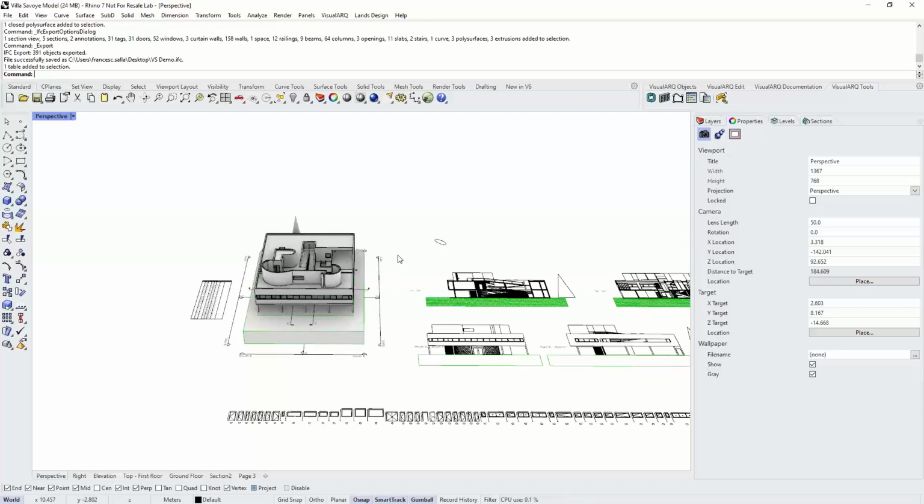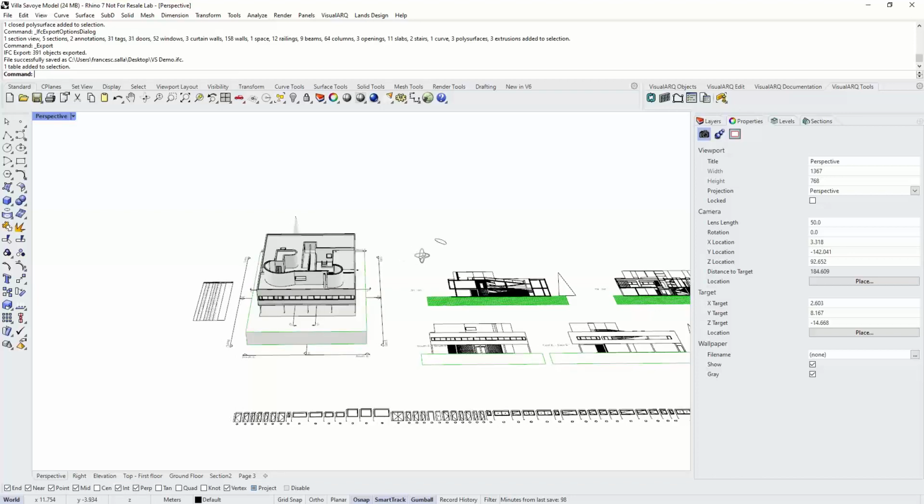You can make clusters in Grasshopper, so you can hide all this mess in a pack, in a component. And this can be used, for example, in different definitions or multiple times, in multiple places. You don't have all these wires, so the definition doesn't look very messy, but it's just pure Grasshopper.